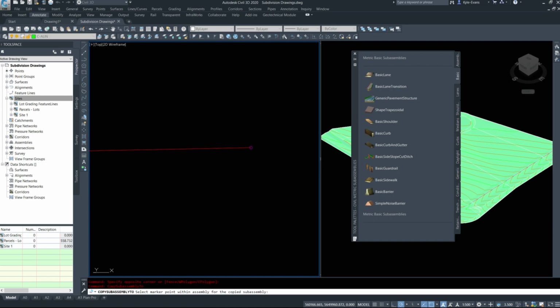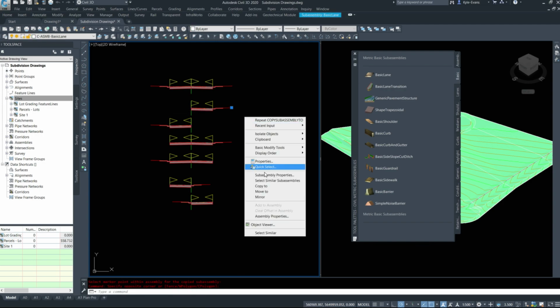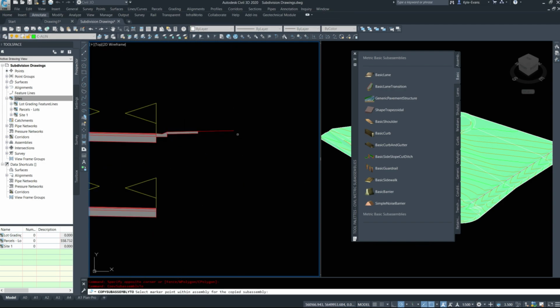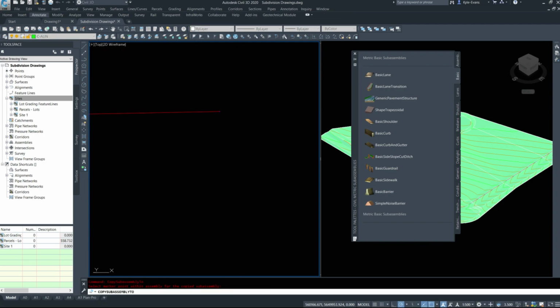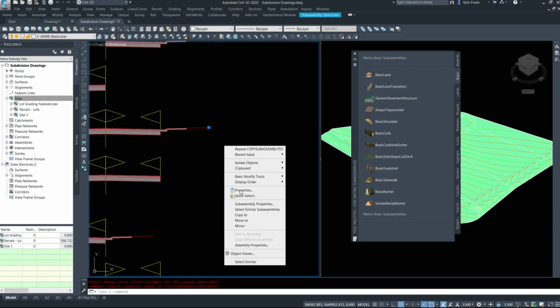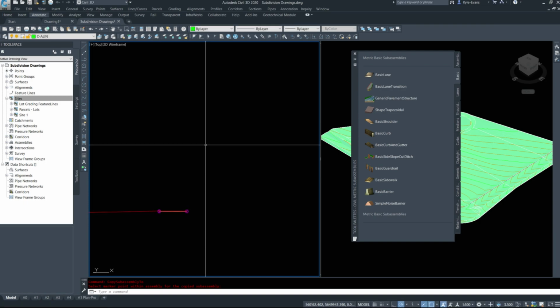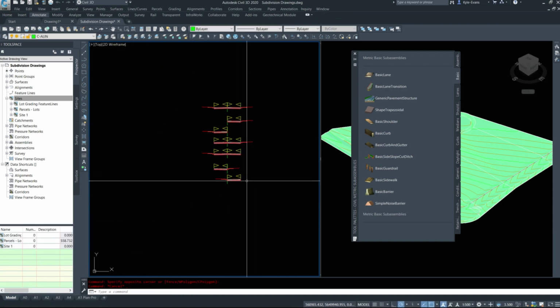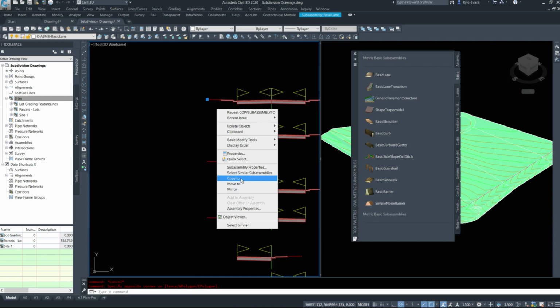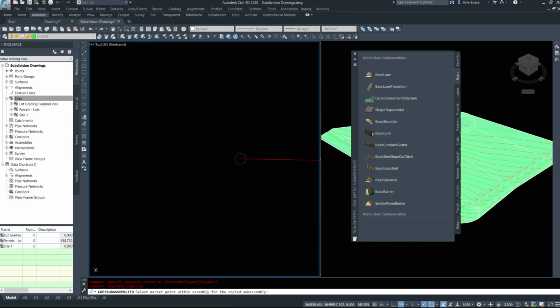So I'm going to copy this through all my assemblies here, and I'm going to copy it to where it needs to go. I know we didn't use all these assemblies, however, copy it to all the pieces just to make sure you have them all and you don't inadvertently miss one or two. Now this shouldn't affect the corridor itself. The corridor should still build and shouldn't be a problem. We're just adding an outside, a dumb little basic lane piece just to extend something.